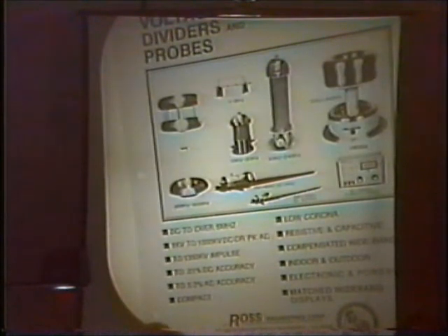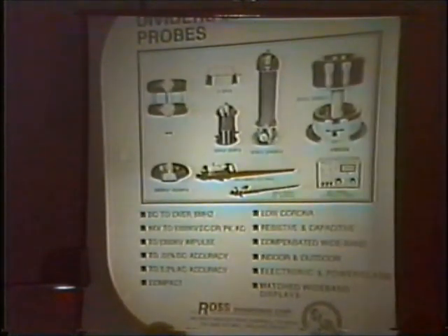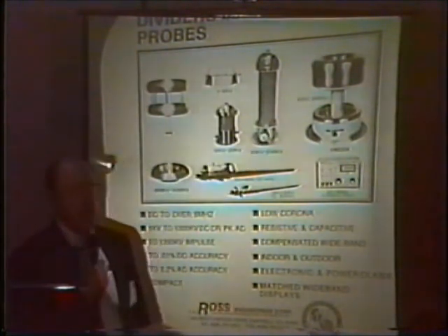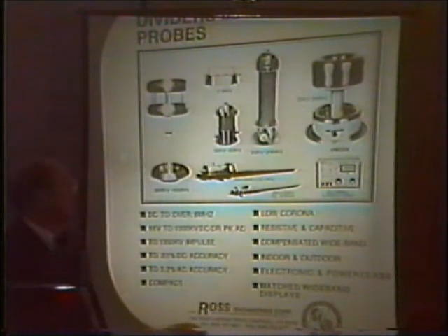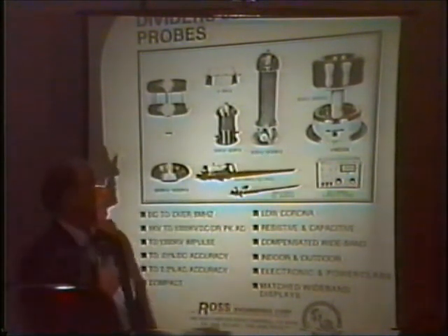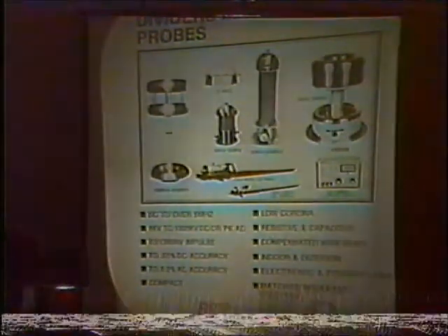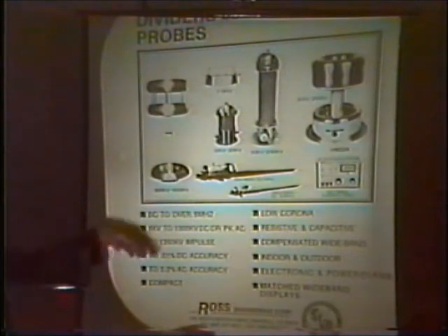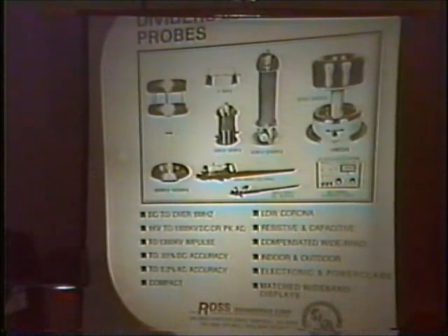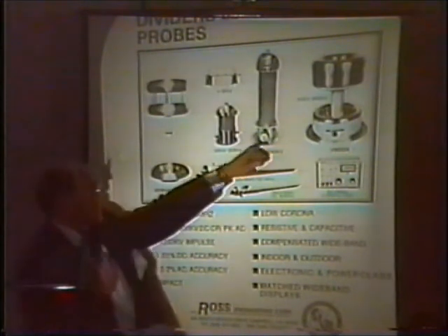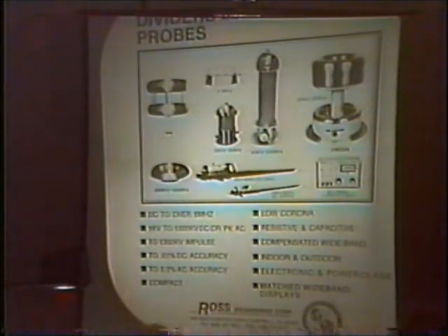Okay, some of the test equipment that we're talking about that you normally use on high voltage devices. These things are voltage dividers, and it depends on the amount of voltage they're made to handle. These come in units between 30 kilovolts and 240 kilovolts. They look very similar to the one you see there, except they start getting longer as you get to higher voltage. And they have certain kinds of filaments inside them, and they are also pressured up. You notice the pressure gauge here, and whenever you've got a lot of voltage and current flowing, it also produces some heat, so your pressure may change on you while you're working.